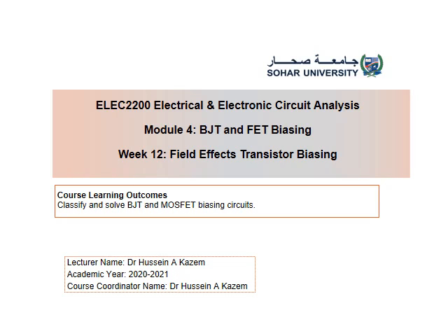We are going to discuss FET biasing now, but just as a comparison, in BJT biasing, we used either the calculational method or the graphical method. In the calculational method, we go through the calculation of IB multiplied by beta to find IC, then we go for VCE, and then you can find other voltages in the circuit.